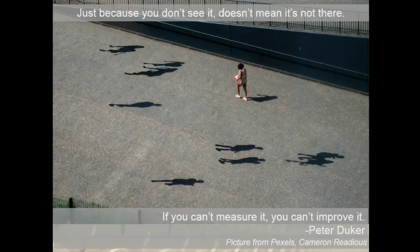The passive layer is invisible. Stainless steel can be passivated or only cleaned. We will see no difference. And its performance in the pharmaceutical industry does not represent an immediately catastrophic risk. With the modern analytic techniques, we can detect the passive layer, prove that the stainless steel is passivated, and we can measure it and see its composition.